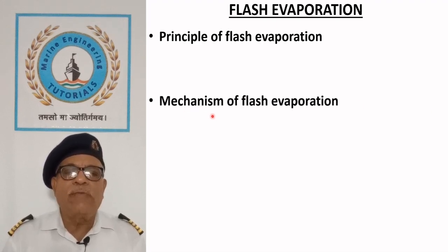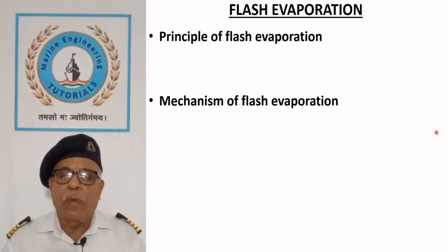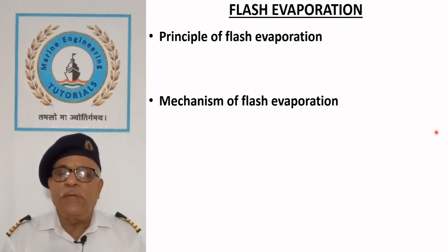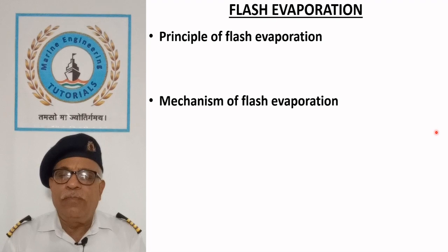Mechanism of flash evaporation. When heated seawater enters into the flash chamber, part of the seawater is immediately evaporated due to low saturation temperature corresponding to the low pressure in the flash chamber.